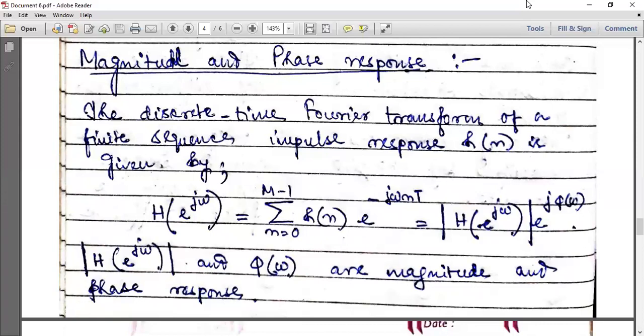Presently you are finding these signals in terms of input and output, so the delay element is needed to obtain those signals. Otherwise you can't insert them in the difference equation. So the above hardware elements will be required for realization of a digital filter.